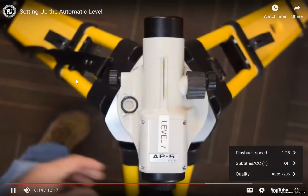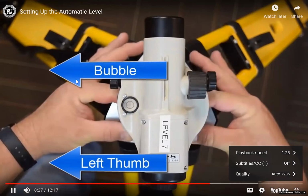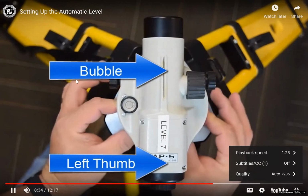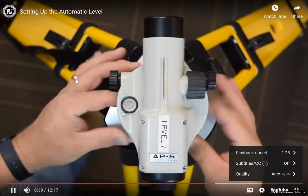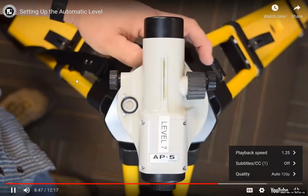So the left thumb rule works this way. With the eyepiece centered between 2 leveling screws, turn those 2 screws at the same speed in opposite directions. The bubble will move in the same direction as your left thumb. Use these 2 screws simultaneously to move the bubble left to right and right to left. Then, to move the bubble forward or back, use the 3rd screw by itself.